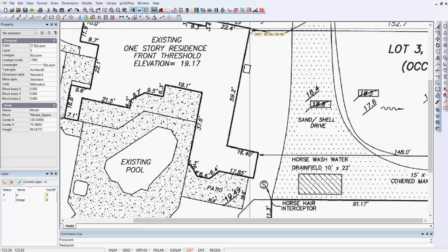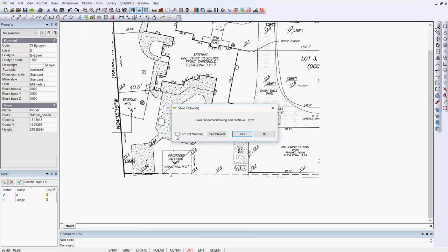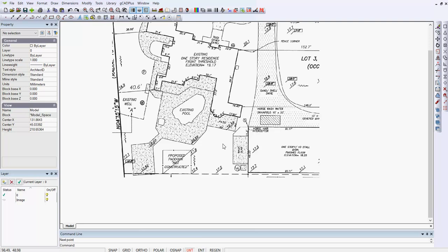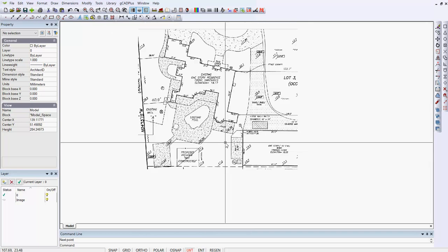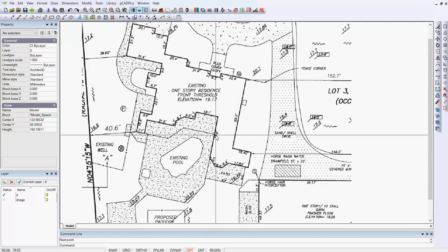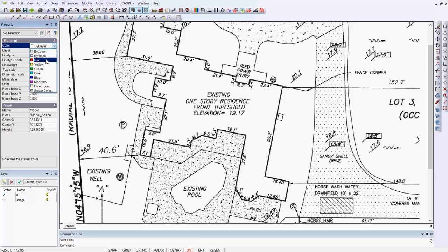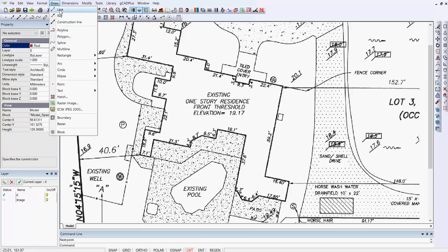Now let's check, by using the distance command, do we get 59.2? So we'll give ourselves the best shot. It's a good idea to scale off the longest dimension that you've got. So how close are we? 59.165, 59.2. So I'm confident now that the image is good. I'll just turn off warning for the moment, but you should not do that. And away we go. So we've still got a drawing called No Name, so at this stage it might be a good idea to save that drawing. So we've now got an accurate base map to work on.